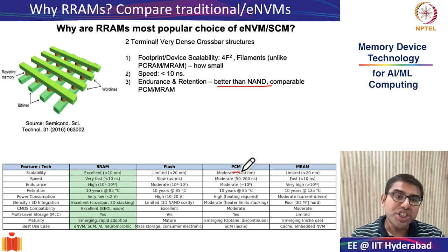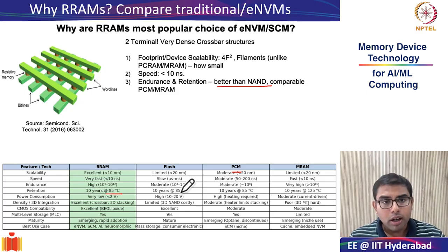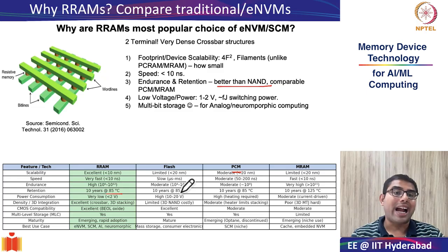Also, the retention of these filamentary RRAMs is very good. It is showing 10 years, which is the industry standard for proving non-volatile memory at 85 degrees Celsius. This is better than flash and almost comparable to PC RAMs. The fourth important point to look at is the